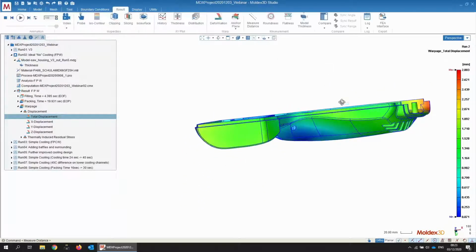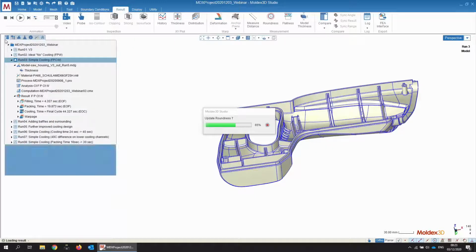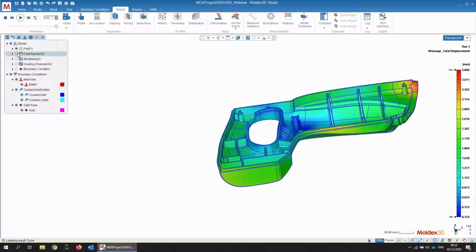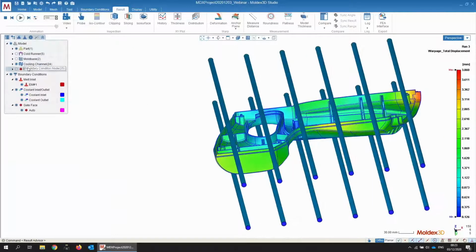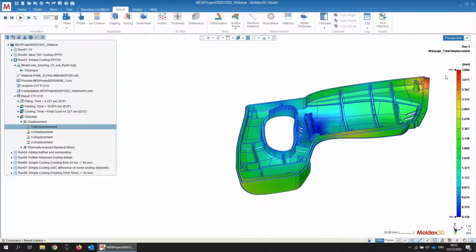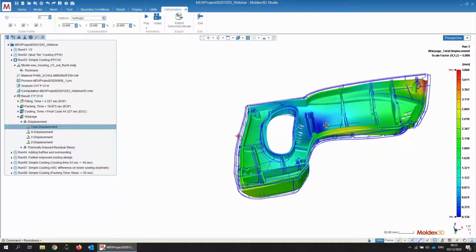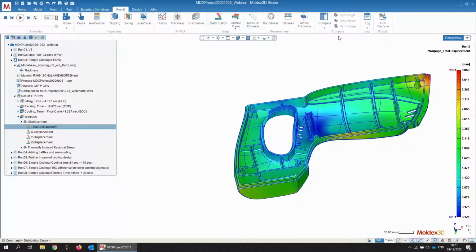Okay. What if we have used the mold that we just designed using those very simple cooling channels like this? You can see from the screen that our warpage situation has been changed. It is now having the same tendency, just that at the corner this is more severe, so we'll end up with 3.8 millimeters. You can also make a comparison with the previous situation.